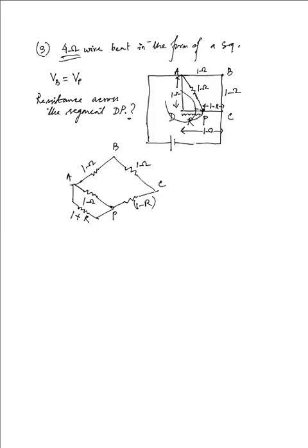And we had given a certain potential difference. Now if we attach a galvanometer over here, this galvanometer shows a 0 deflection. That means Ig is 0, and this is simply the balanced condition of the Wheatstone's bridge, isn't it?